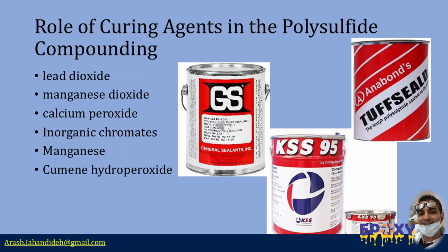Originally, polysulfide rubbers, often called thiocol, were solid materials with very high sulfur content. Early development treated these materials similarly to other rubbers, curing them with sulfur and zinc oxide. However, the introduction of a liquid polysulfide polymer in the 1940s expanded the possibilities for curing agents and accelerated their commercial use. Liquid polysulfide polymers can be cured by a variety of compounds through different reaction mechanisms.